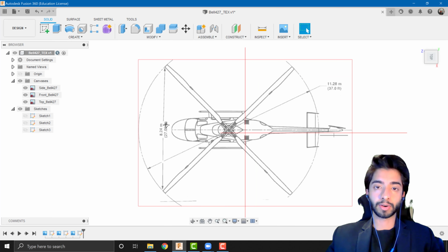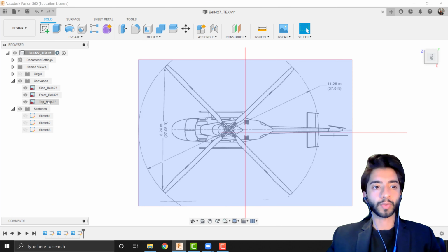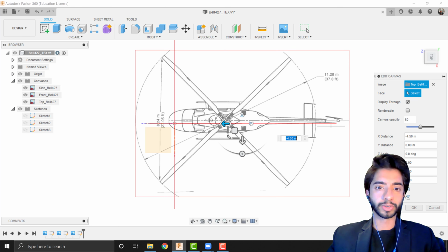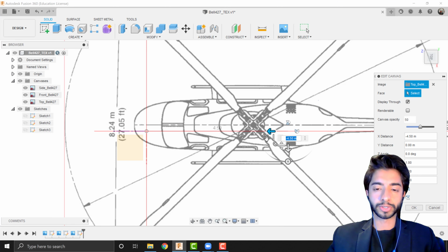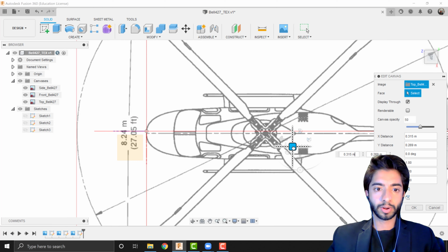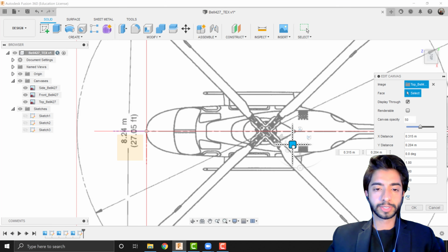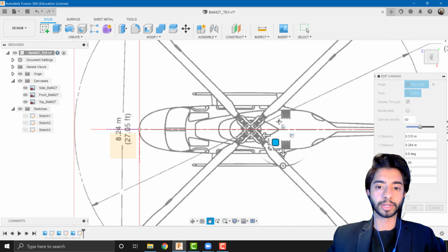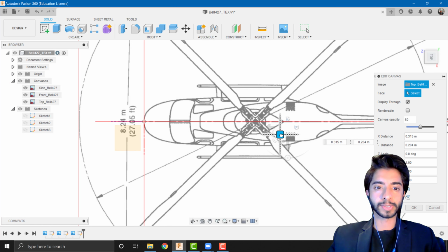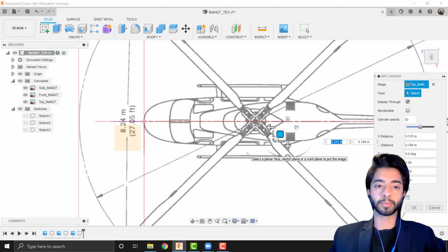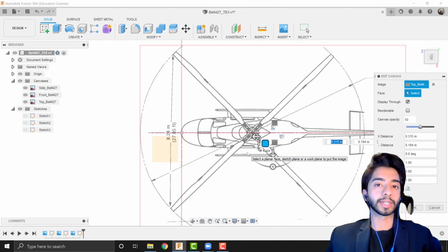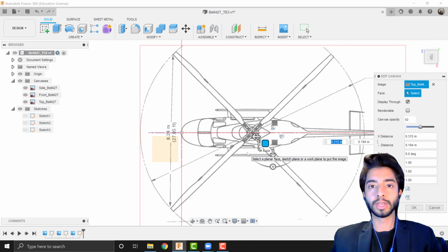Hopefully now it's scaled correctly, but we also want it to be in the correct position. So right click on the top view, edit canvas, and move it till the nose is on the origin, so perhaps somewhere over there. You can see that in this case it's doing relatively well, because the line of symmetry on top of the blueprint lines up horizontally as well, which is a good sign. Even though top to bottom it's not vertically straight and is on a bit of an inclination, that doesn't matter to us too much as long as the line of symmetry is still correct.